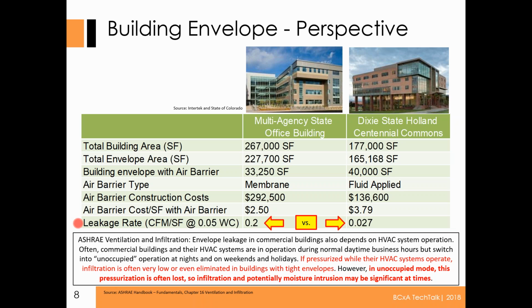You want the question again? Yeah, well, it sounds like the return fan's pushing back into the building. So read that one more time, please. What has your experience been with pressurizing buildings with return fan systems versus relief fan systems? And then he mentioned he recently came across a system with a return fan that would draw air in backward through the relief duct when the return fan was slowed to create back pressure in the space.